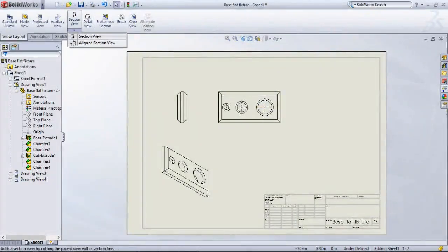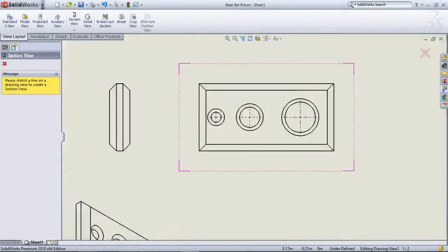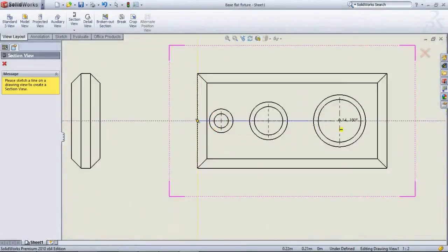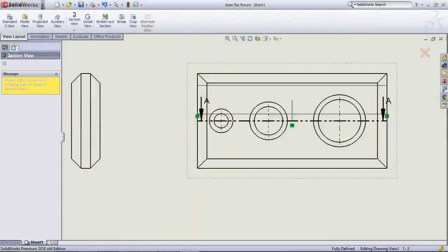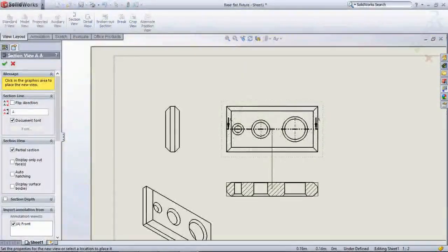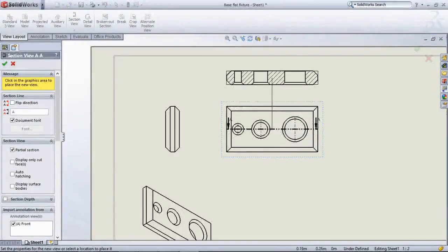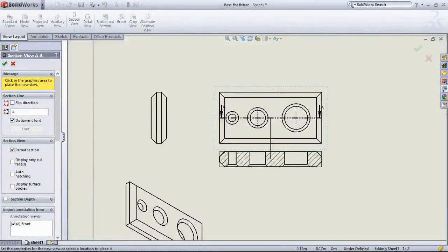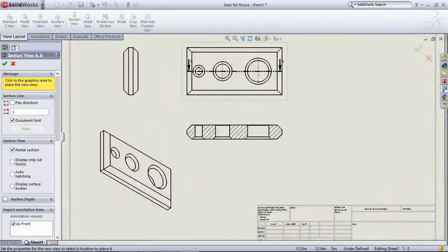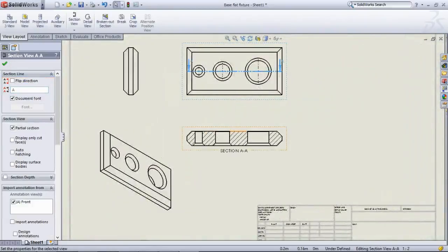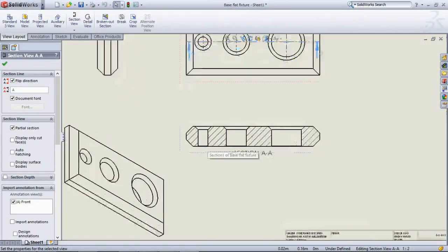After creating the projection, I'm going to draw a section view of the top view. From that top view, we can project a front elevation by clicking the sectional view button in the tab, which is shown in the video here. Just after clicking that, that view will be projected automatically here.